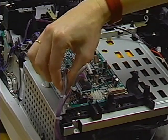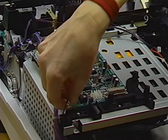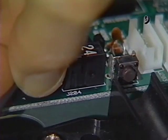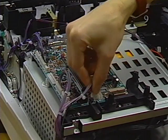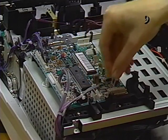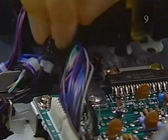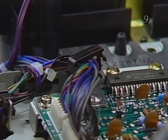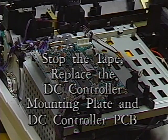J205, cassette feeder PCB cable. J204, optical fiber cable. J203, scanner motor PCB cable. J202, laser assembly PCB cable. Finally, replace the connector cables inside the two black cable clips. Stop the tape and replace the DC controller mounting plate and the DC controller PCB.